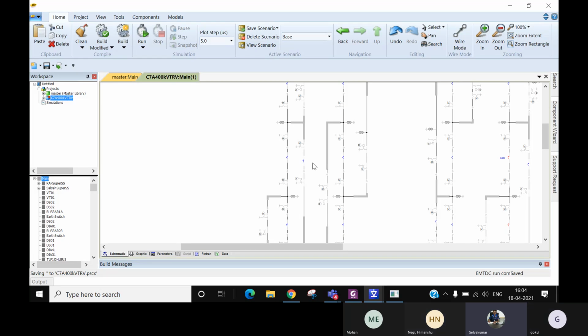To model that, you have to model this breaker in detail with some ABCD parameters. I'm just trying to say what we have not covered as a part of this. So you have to model it as a part of ABCD parameters, and such parameters you have to obtain from the manufacturer only, or that study has to be performed by the OEM rather than the consultants.